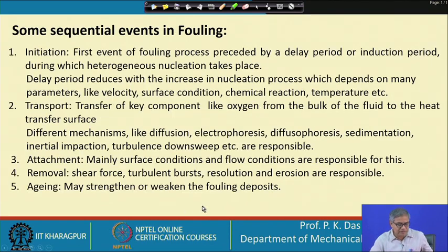Let us go to the next slide. Some sequential events in fouling. Initiation: the first event of the fouling process is preceded by a delay period or induction period, during which heterogeneous nucleation takes place. This is very important. Fouling means a new species is coming that was not there in the original fluid, or that was thoroughly, homogeneously mixed in the fluid stream.